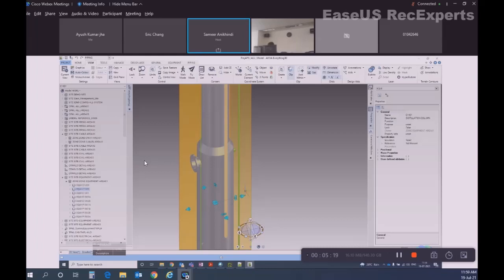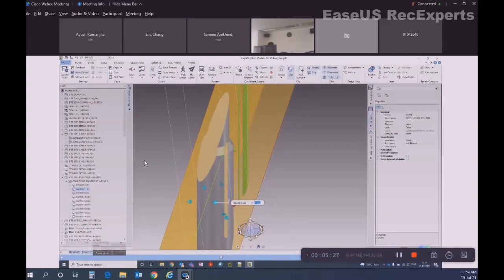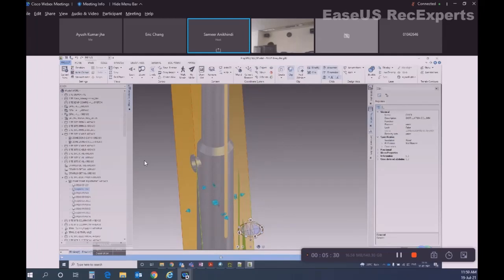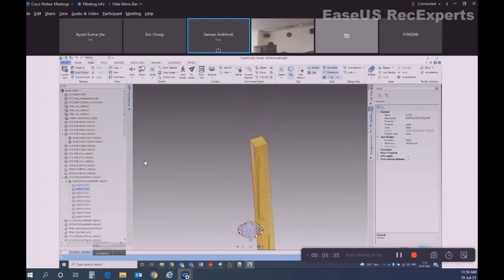There are three kinds of grip. One is the extension grip, this one. One is the rotation grip, you can rotate. See this one. And then there's a relocation grip, the center, so you can move the clip box somewhere over here. Getting it? Rotation grip in three different planes, extension grip at all faces, and relocation grip means change the center of the clip box.